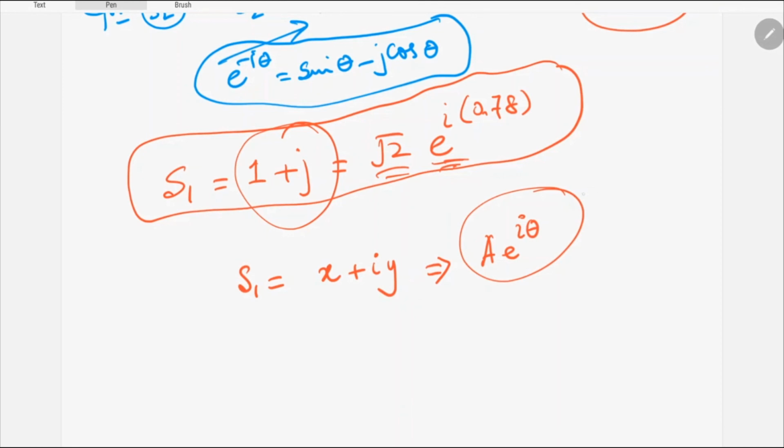One application that comes to my mind is the Nyquist plot. When you're trying to understand the Nyquist plot, you will see that when we define that we have to sweep the frequencies from 0 to infinity, then to understand how the Nyquist plot will behave at infinity, this form of complex number representation serves a very good purpose, right?